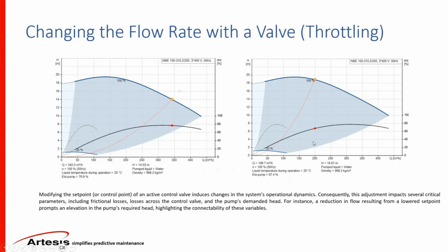So this is similar to, let's imagine a car where you're pressing the gas pedal at full throttle, and at the same time you're braking, right? So this inevitably will cause some inefficiency. That's also manifested here in a pump application. While you're keeping the speed at the same constant rate, you're throttling the pump, which will of course create inefficiencies, and that inefficiency will show itself as heat.